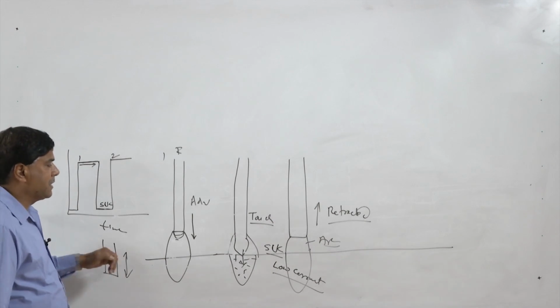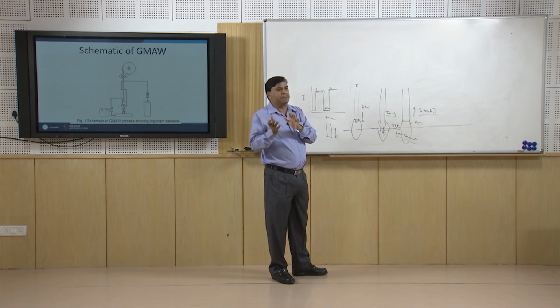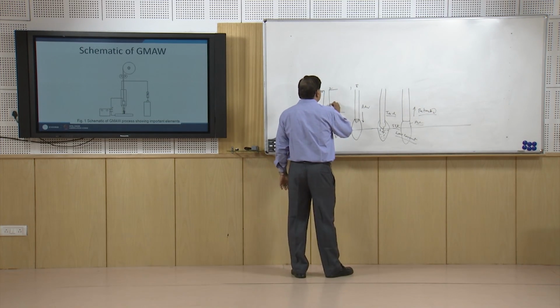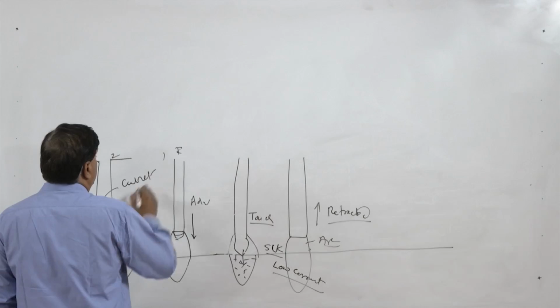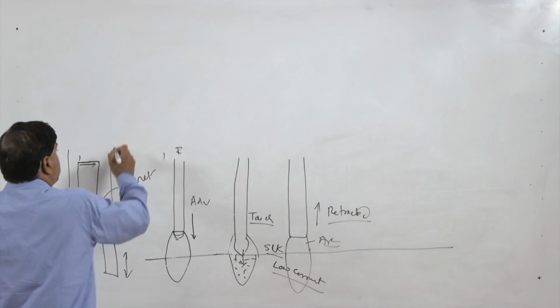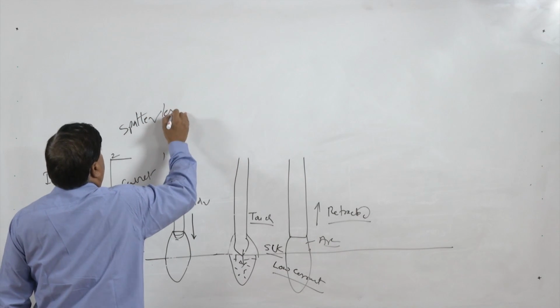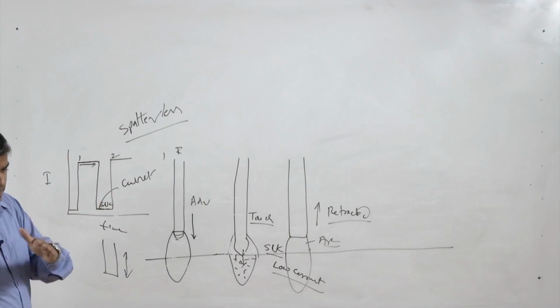Once it touches, the transfer of the molten metal to the pool takes place. At this moment, the current value is very low. So, very limited current facilitates spatterless transfer. Here the unique feature is spatterless transfer, and the condition when the transfer takes place, the current